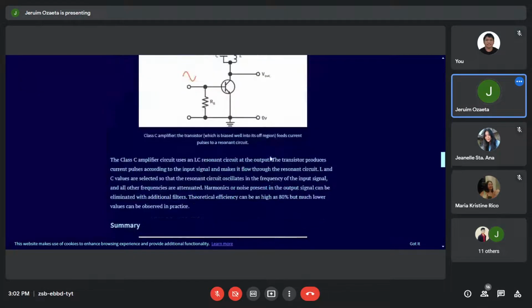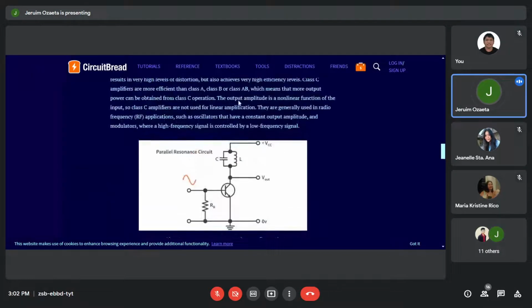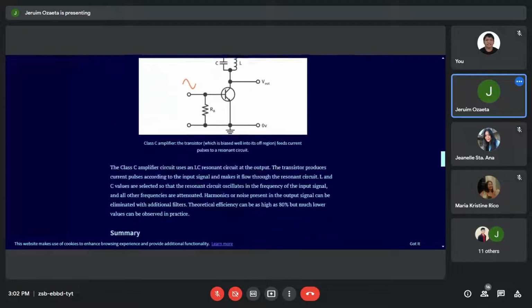Why is it less in both? Because when the input current moves away from the resonance frequency, the filter will act as if at a lower frequency with a higher resistance, or at a higher frequency, also with a higher resistance. So the output will decrease, because, as I said, it's a resonance circuit.